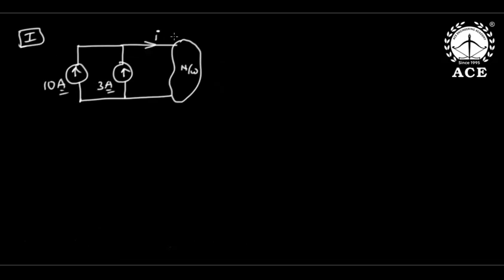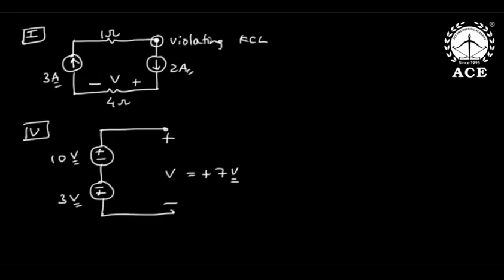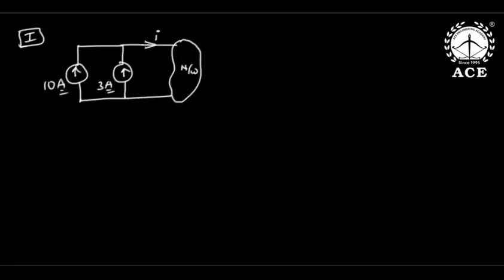That means we can connect current sources in parallel, sir. That is not an issue. Previously, current sources in series was a violation of KCL, but current sources in parallel is okay.